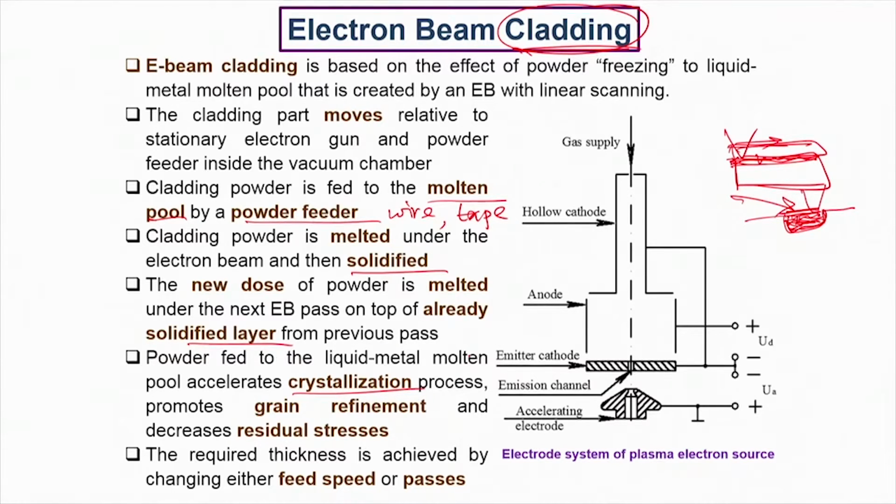The liquid metal pool which solidifies within this gap, say for example if this was the gap and you have filled it up with the powder and then you're melting, or you're feeding filler metal and just allowing the liquid to flow in and cover. In such situations, when the melt pool solidifies, you actually can't make out any difference after this, and there is no need of any surface machining or any other post treatment requirement. There is no further annealing or anything required, because this volume is very small, is the same composition as here, and there is very good wetting here inside the cavity.